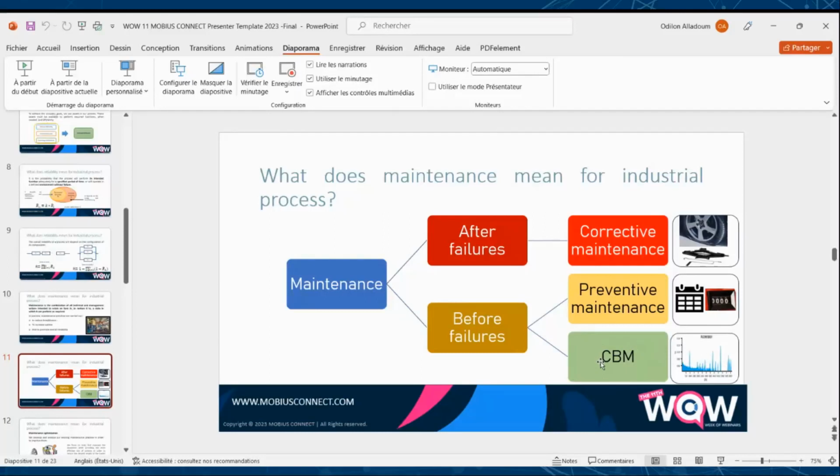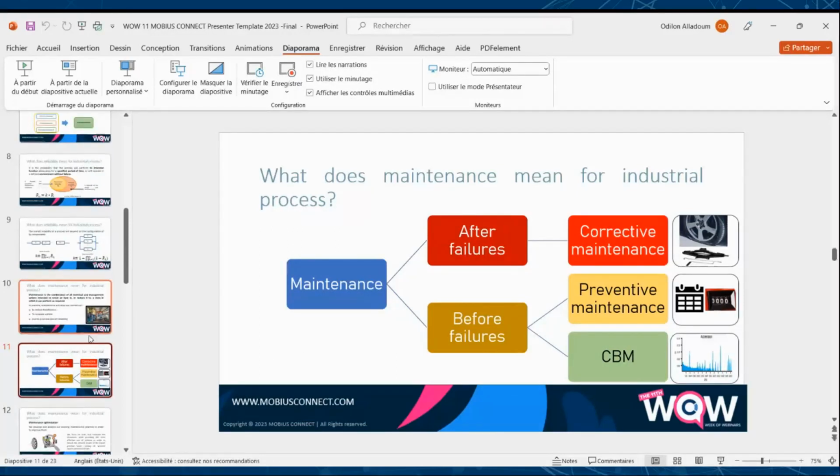In addition to preventive maintenance, we have condition based maintenance, also called CBM or predictive maintenance. The goal of this approach is to identify proactive activity to carry out at a scheduled time when the maintenance activity is the most cost effective and before the asset failure. CBM uses technology like vibration analysis, oil analysis, infrared thermography, etc. So CBM provides good savings compared to preventive maintenance.